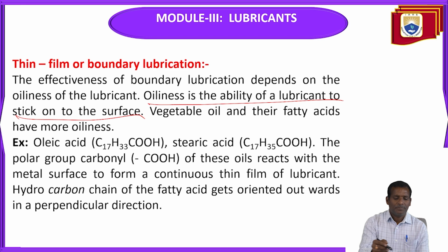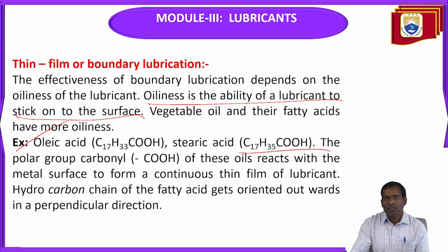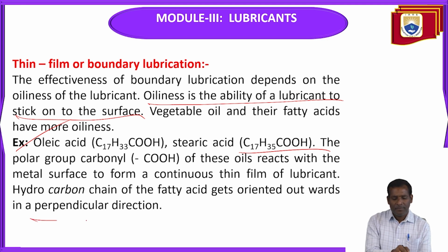Example: oleic acid, C17H33COOH, and stearic acid, C17H35COOH. The polar group, carbonyl, of these oils reacts with the metal surface to form a continuous thin film of lubricant. The hydrocarbon chain of the fatty acid gets oriented outwards in a perpendicular direction.